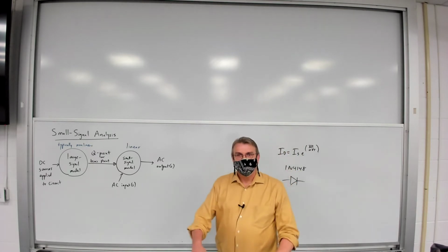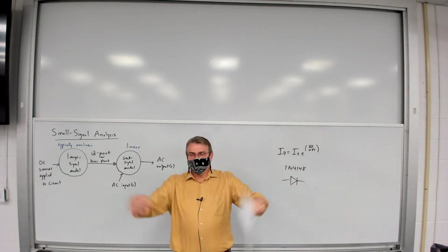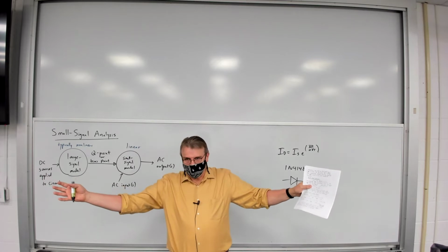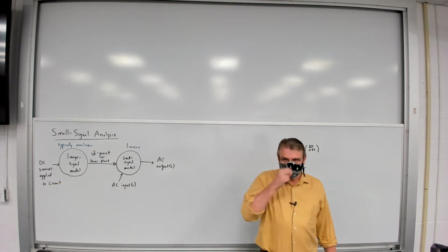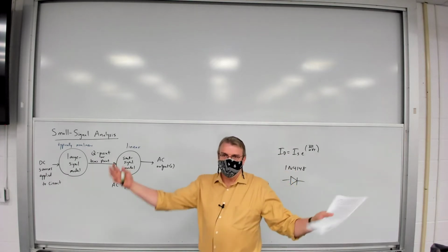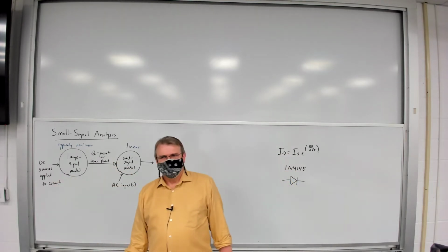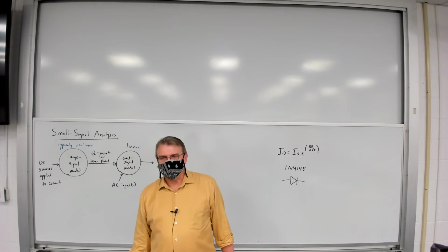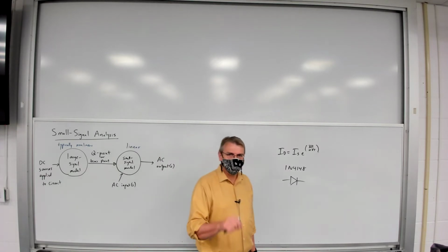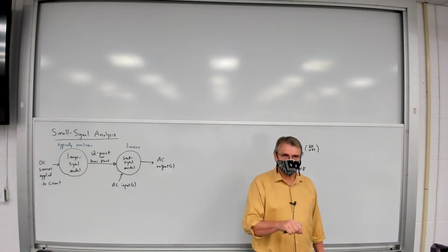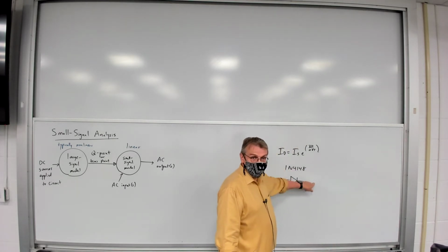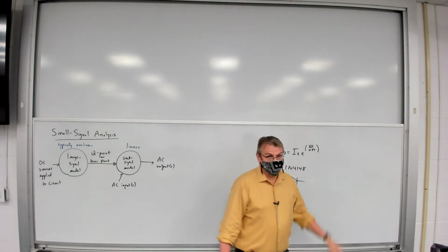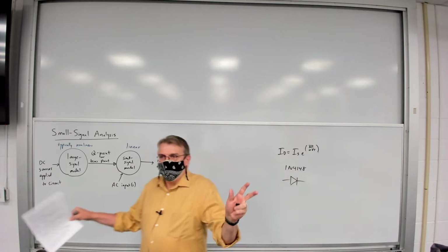As I said, obviously, if they're orders of magnitude different, there could very well be something wrong. There probably is something wrong. But if you're seeing tolerances of 20%, 50%, something like that, it doesn't necessarily mean there's anything wrong. It simply may be that for the particular circuit you have built and measured, you are seeing variances from the simulation model and from the ideal calculations. I always want to bring this up.